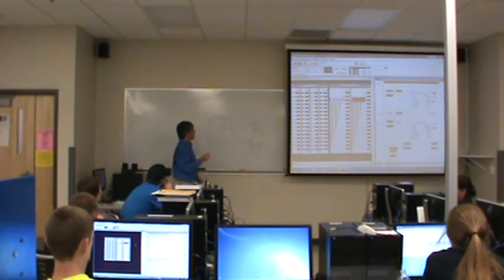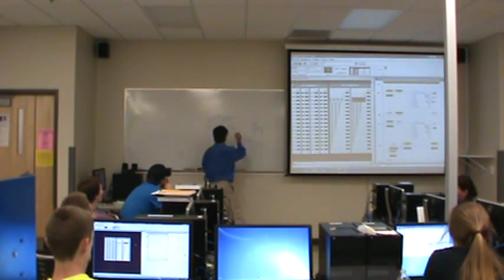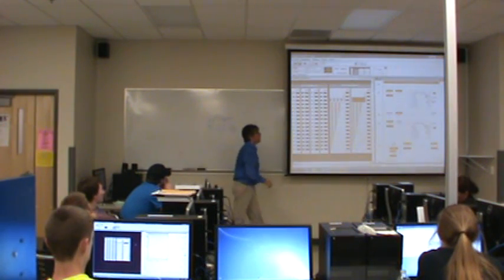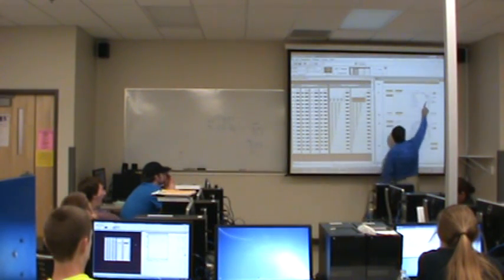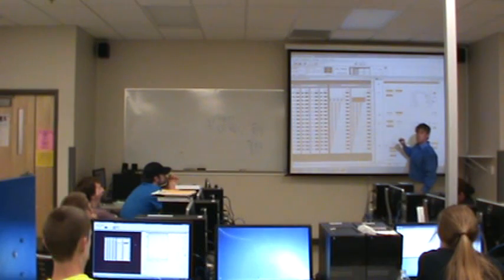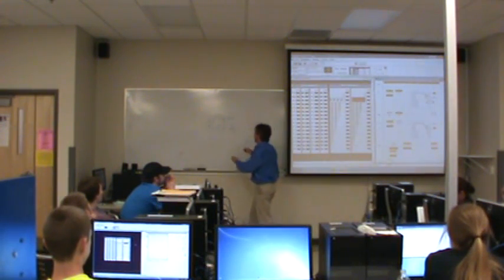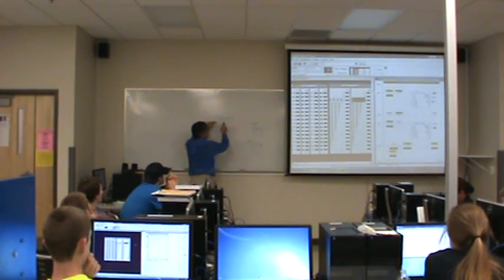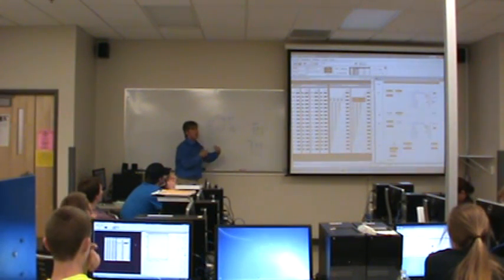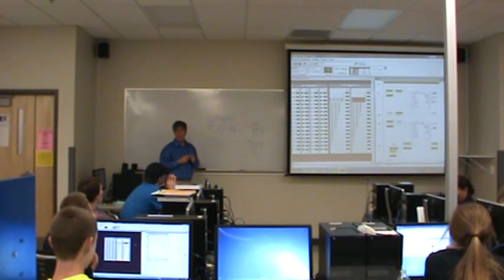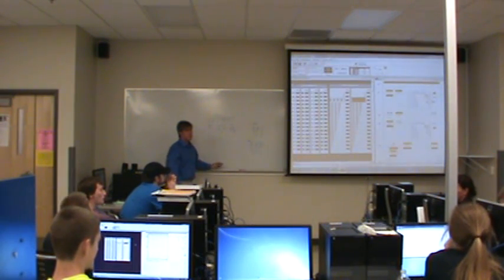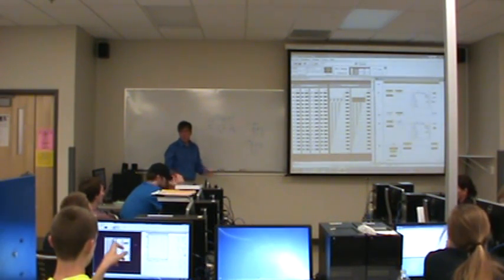And then, when I want to compare this to what's in memory, I'll make sure that in the memory location, I have set those bits off. Does that make sense? Okay. So that part will always match. In other words, I will effectively ignore all the inputs except the ones that I'm allowing to get through by the mask. Okay? Any questions on that? So that's the idea of a mask.